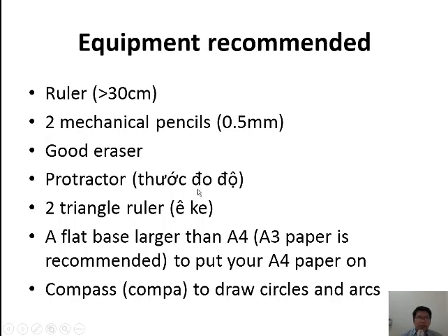The equipment recommended for you: you need to have at least one ruler which is longer than 30 centimeters. You need at least 2 mechanical pencils with 0.5 millimeter leads, maybe one HB and one B. You need a very good eraser, a protractor, and 2 triangle rulers, the standard 45-45 and 60-30. You also need a flat base larger than A4, because in our course we only use A4, to make it easier for you.